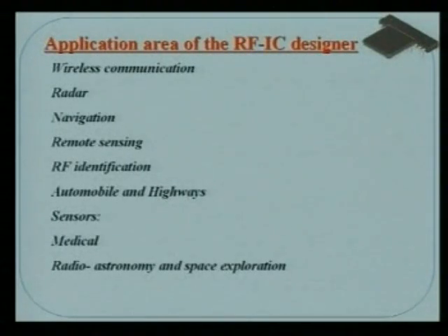So the basic thing is you have to catch the signals at high frequency by the analog front end or RF front end, then down convert it to the baseband, and then do digital or further processing for the baseband. That's why it is omnipresent, in your cell phone or any wireless application, you will find the RF front end. So that's the motivation.